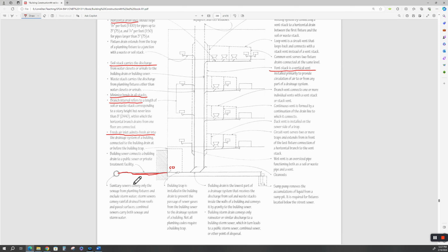And I wasn't going to let them tunnel underneath that thin slab to redo that sewer line, because there's no way they could get that soil compacted. I don't care what they say. There ain't no way on God's green earth. It's just like we talked about underpinning slabs many videos ago. There is no way you're going to completely consolidate that soil after tunneling underneath the slab or underpinning to 98% compaction. I don't care what they say.